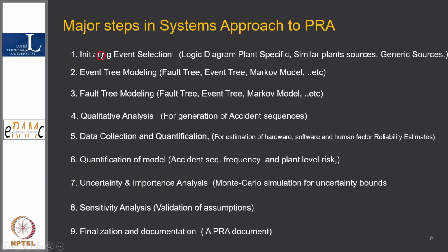In fact, if we do this in a computerized environment, then the component itself is characterized with uncertainty, or error factor, which is called the error factor. Since the component has uncertainty associated with it, the top event, that is unavailability, and subsequently at the plant level also, we get uncertainty.